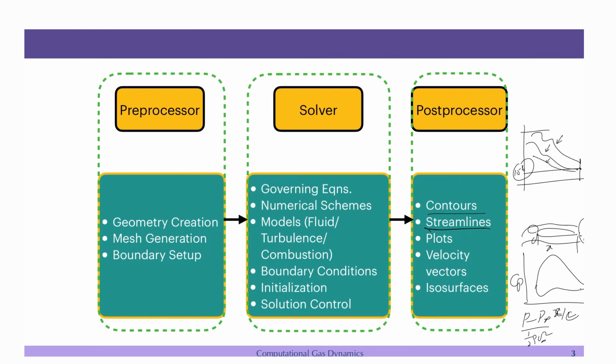So, how the pressure is varying? If you are expecting a lift, are you getting the lift? If it is 0 degree of attack, let us say it is symmetrical, then maybe both the pressure and suction side will nearly overlap. So, you will not get any lift. If you increase the angle of attack, you should get the lift. So accordingly the Cp curve should change. So that will give you a lot of information.